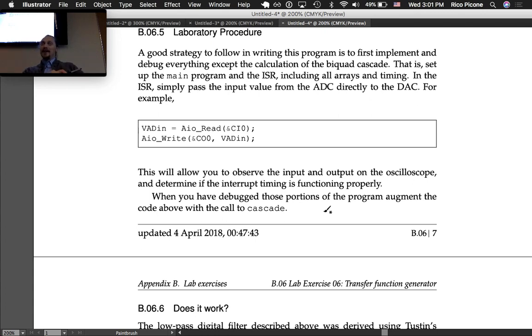So it has to do the A to D conversion, and then it has to do the D to A conversion. So that takes time. I mean, this is a pretty fast little machine, but it will take some amount of time. You should be able to zoom in on the oscilloscope and see that there is a little bit of time delay there. And that should correspond approximately to your BTI, your half millisecond. So it should be about a half millisecond.